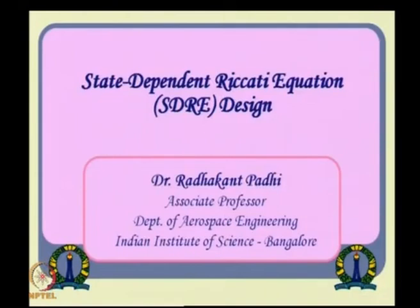So, we start with SDRE design. It has become quite popular, because it is the simplest form of nonlinear control design, nonlinear optimal control design, that I can think about. The whole idea here is you somehow repeatedly use the LQR solution that we know. So, let us see how things proceed. It will be very apparent and very clear very quickly.